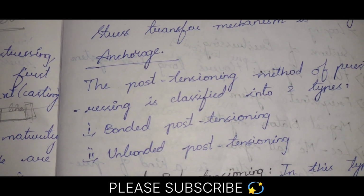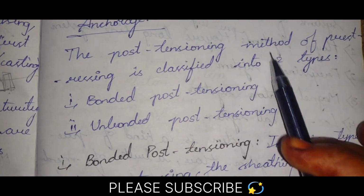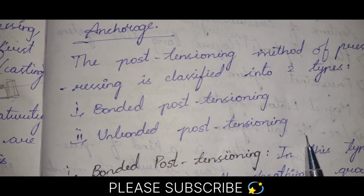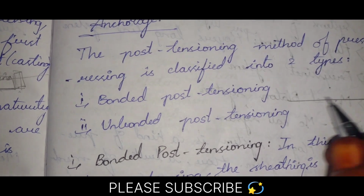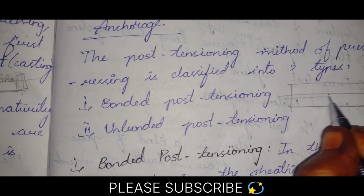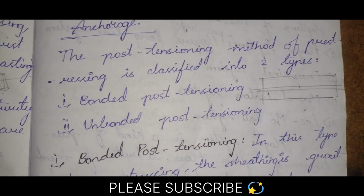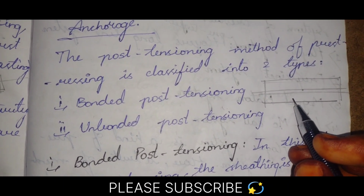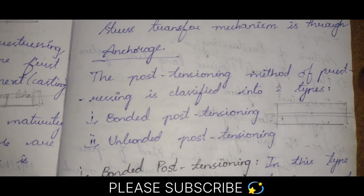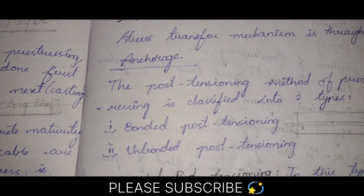Coming to the anchorages, the post-tensioning system has two types: one is bonded post-tensioning, second is unbonded post-tensioning. I told you that first the casting of concrete is done, and in this we provide some gaps, ducts. We see this in metro pillar constructions, right? Generally some gaps are provided in them. The wires are placed in them and post-tensioned after the casting of concrete is done. That is what we call post-tensioning systems.